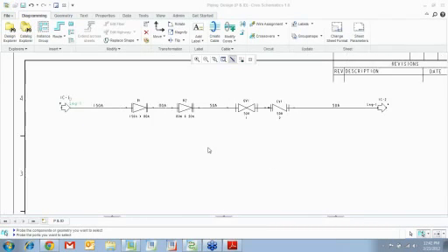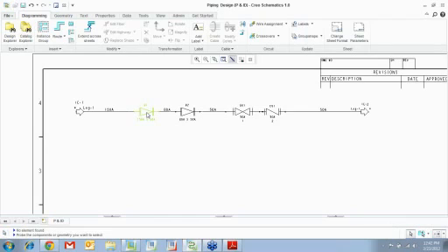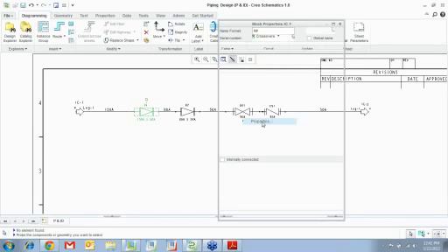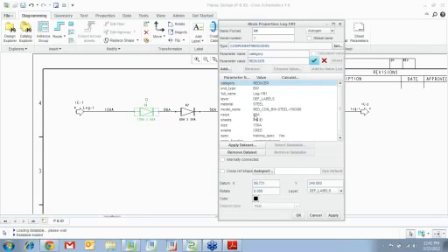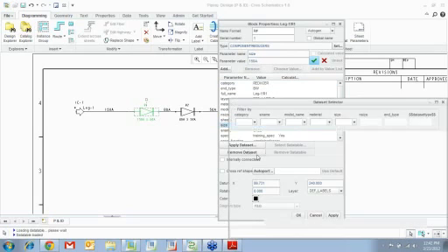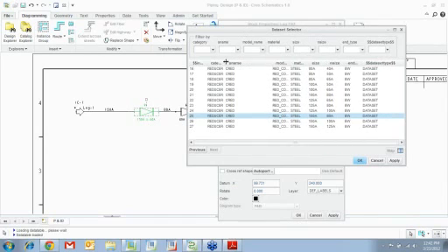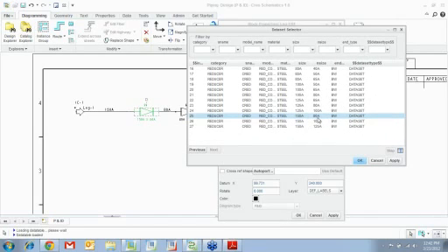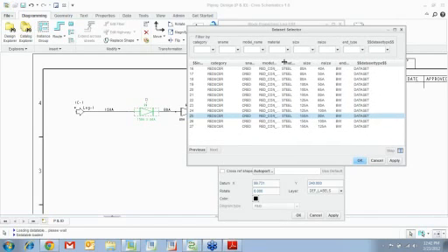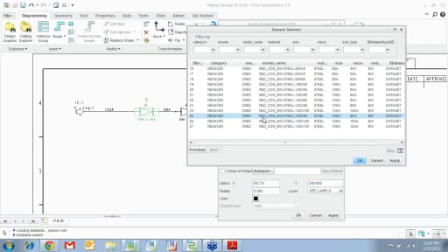Okay. Now, similar to that, we also have valves. So I select that, go to the properties. You notice that you have all these properties, different sizes. So it's going from 80 to 150 to 80. You can apply a data set, and you can see, hey, I want to go from 150 to 80. And notice it automatically picks the right size part. This is the name of the ProE part that it needs to use. So this is like a data set that you can fill up in Excel, and you can load it one time, and that's it. You never worry about it again.